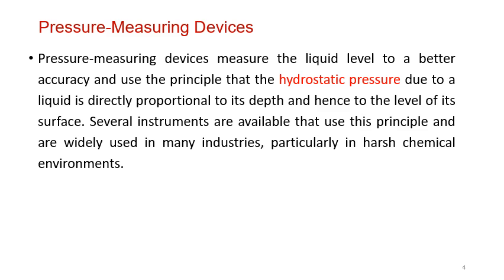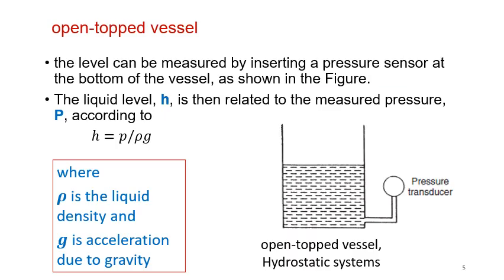The pressure measurement device. In the pressure measurement device, we have two techniques. We are going to study them after this. We will see them after this. Like the open-topped vessel. This is the vessel and it's open from the top. If the case is like this, we will have a pressure transducer or pressure sensor here, which will measure the pressure caused by the water level.